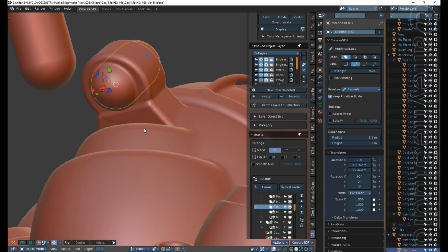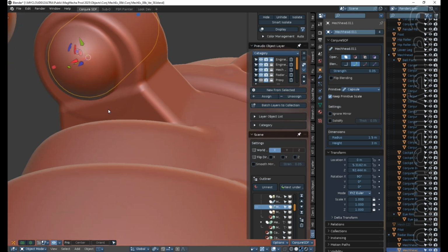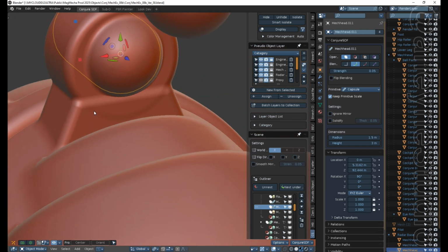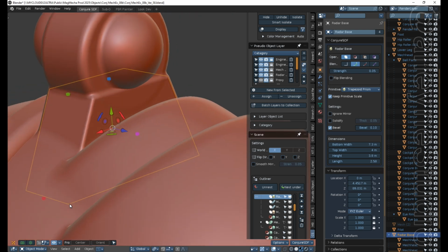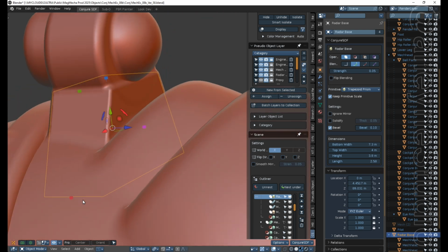These subtle little indentations could be cleaned up here, but they won't show up in the final render. They won't show up in the geometry bake. By the time I tell this guy that his bevel is like 0.05, or when I go for final, 0.1, all of this section is just going to be empty polygon in the very end. So I'm not concerned.